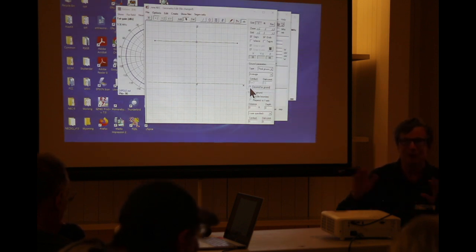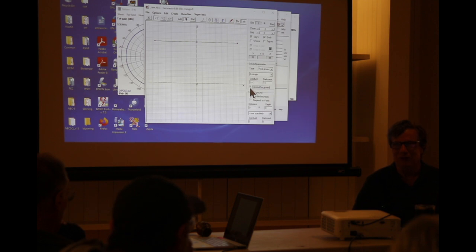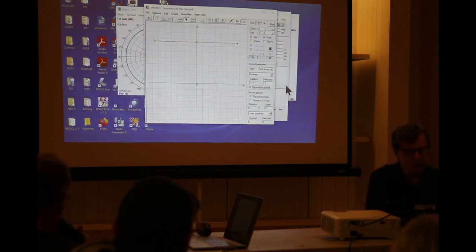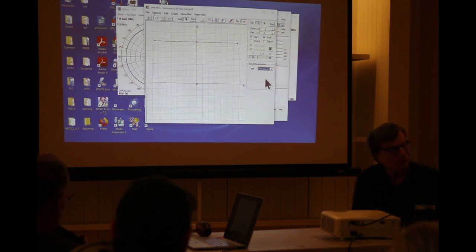Okay? When you start working DX, you may want to be 100 wavelengths away to really define things. So this will go out maybe 10 wavelengths here on the real ground. So we won't use the extended ground at this time. But let's put a perfect ground under here. So let's see, here's a perfect ground, assuming the earth is paved with copper, okay?